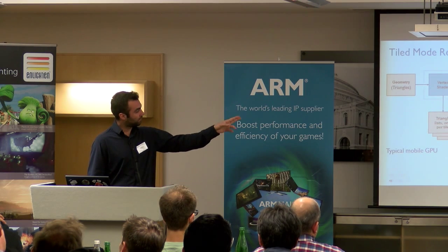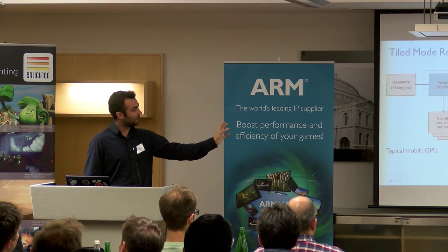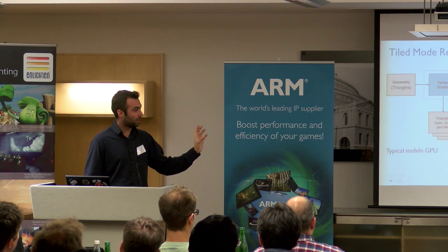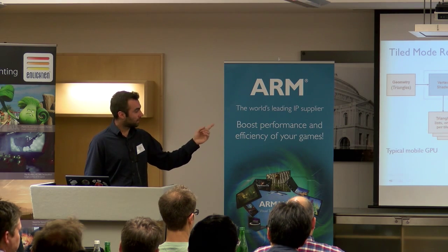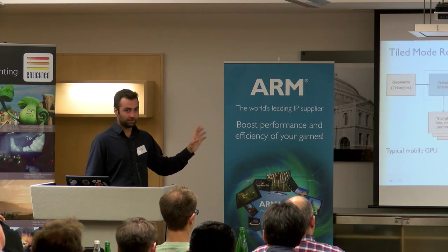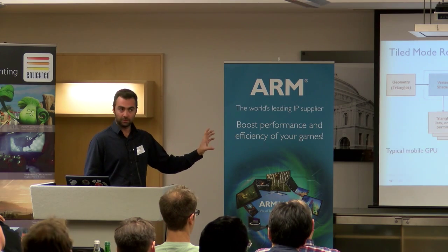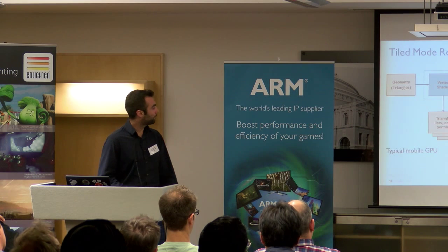And then at the final stage of the pixel processing, we have the tile buffer, which is an internal SoC memory, and you only go to external memory after you have finished processing the complete scene within this tile.